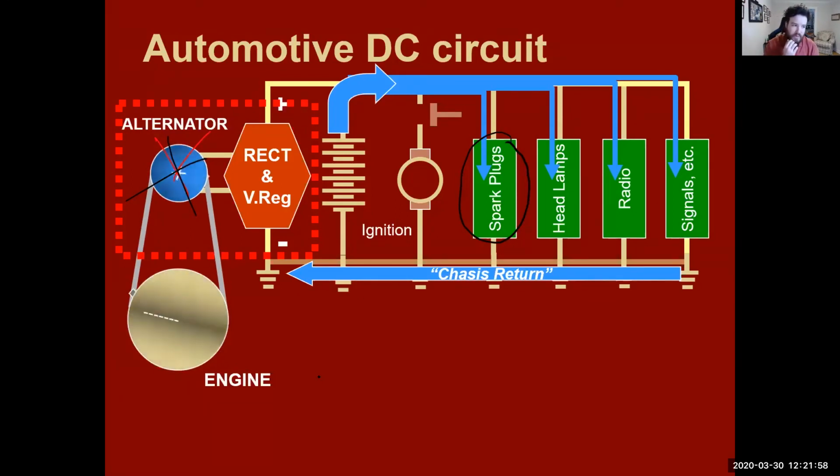Whereas instead of putting a flame to a candle, we're jumping two leads and getting a spark between the two. We're using an electric source to go through the two, and as it goes through, fuel combined with air gives us our ignition. In a diesel, we have a volume of air that is compressed. It heats up because it's compressed, and at the top most of its compression cycle, we atomize fuel and it gets squirted in and it explodes, and we have a power stroke.